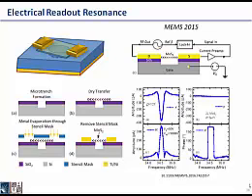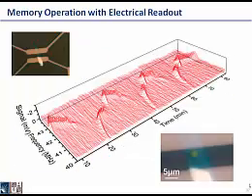And we can read out the mechanical resonance electrically using a downmixing technique, which we reported in detail in this MEMS paper earlier. It should be 2016. Apologize for the typo. So basically, the resonance, if we tune the phase correctly in one channel, should show as a sharp dip. And indeed, that's what we observe. Just to make things easier to see, I flipped the vertical axis so a dip shows as a peak in this plot. For this particular device, it's a 3-layer MoS2 resonator over a 3-micron hole. As I change the temperature, we can see it's switching back and forth between different states.